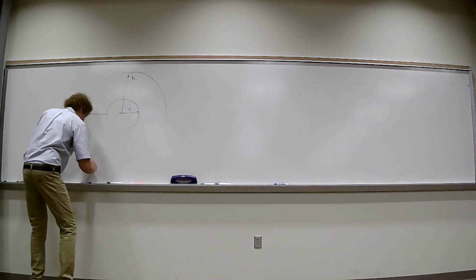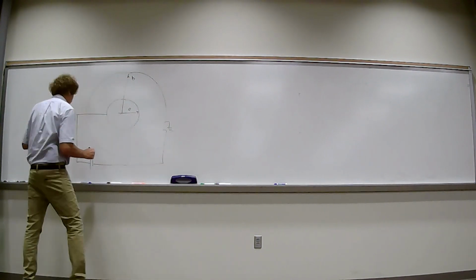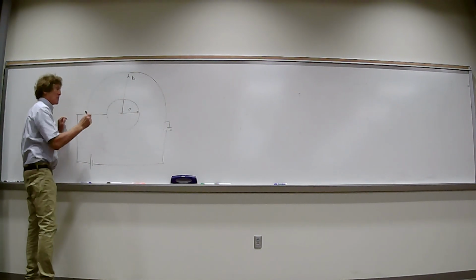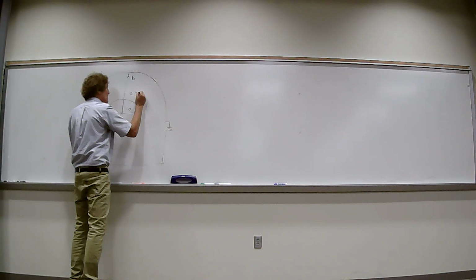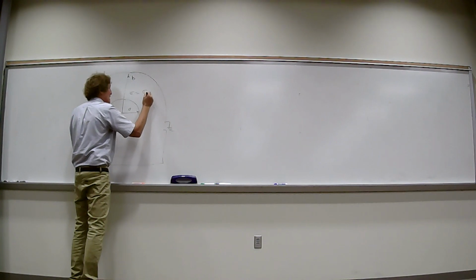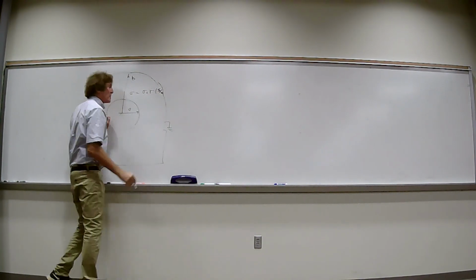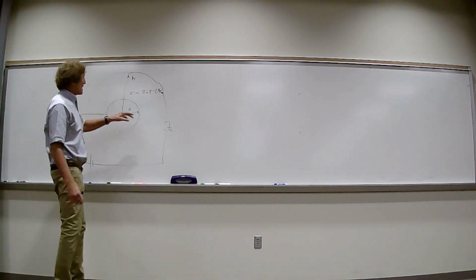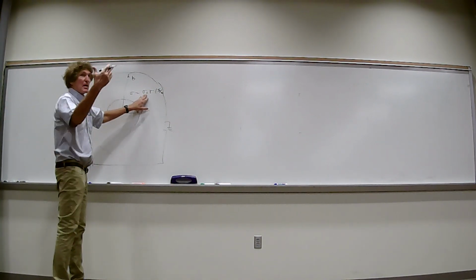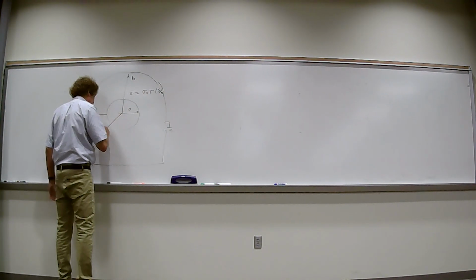I do this only to help people get a good mental understanding, and then ground the outer layer right here. And I'm going to put a conductivity, but this conductivity inside here is going to be some sigma 0 times r, and the units would be Siemens per meter. Y'all follow me on that? So basically, I have a conductivity. I didn't specify sigma naught, but it's sigma naught times r. So the further out it goes, the larger the conductivity. Can y'all follow me? And again, r is measured from the center.